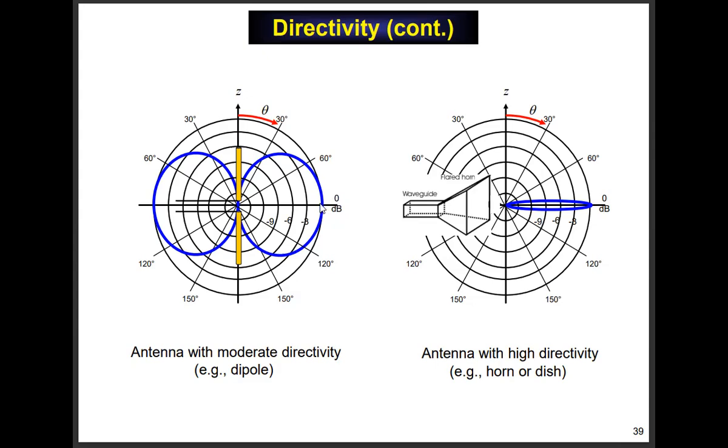And it's a good antenna for wireless communications. If you're trying to communicate with a user on the ground, you want maximum radiation in the direction of the ground. Here's a user over here in the far field somewhere. And not only that, but another advantage is it's omnidirectional in phi. So if you're communicating with some mobile user in a car or something, they're driving around, you want omnidirectionality, right? So it's a good antenna for that.